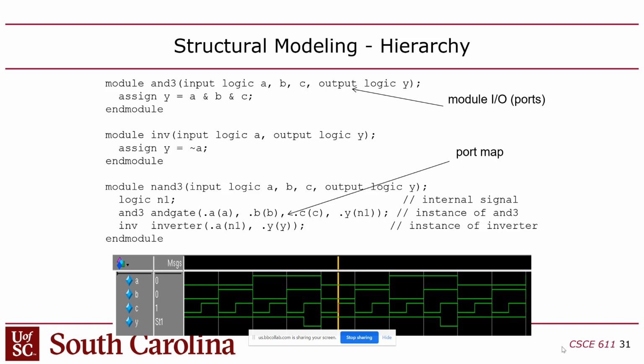And so there's my simulation, a little redundant. I ran it a little too long. You can see the cursor there, and you can see the corresponding values there. Sometimes you'll see Verilog marks this as a strong one, and these are not strong. I never figured out what the distinction is. But clearly it's a 1, right?